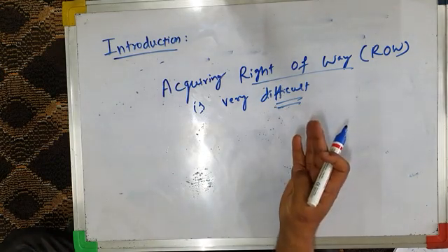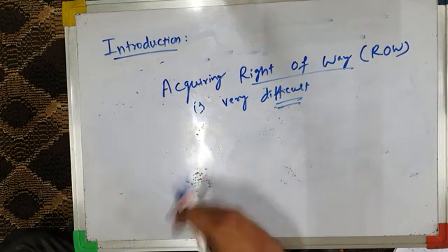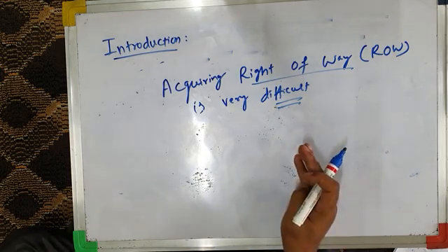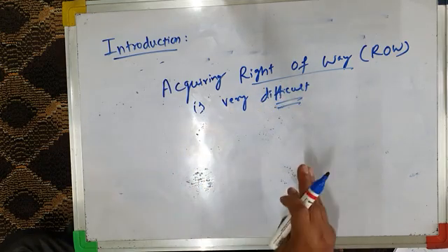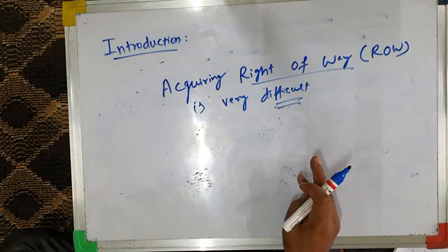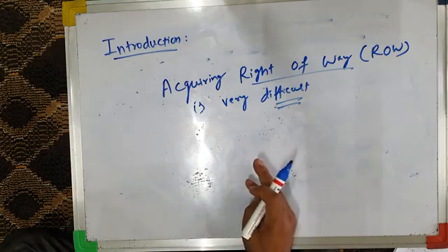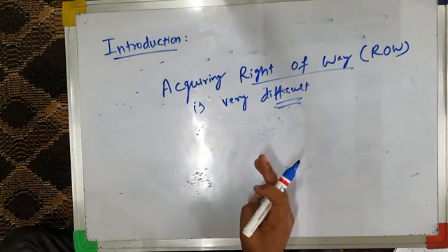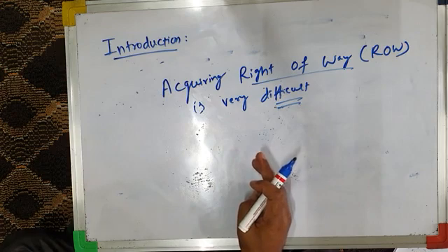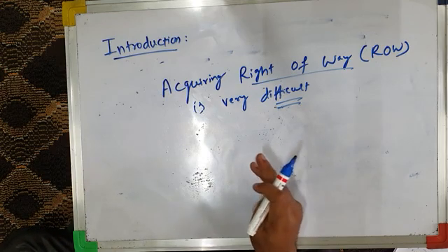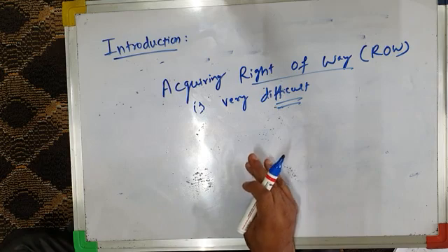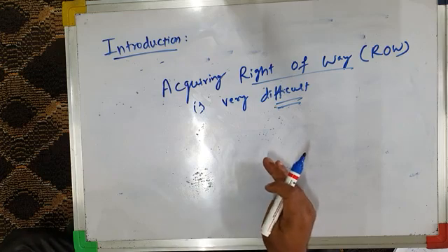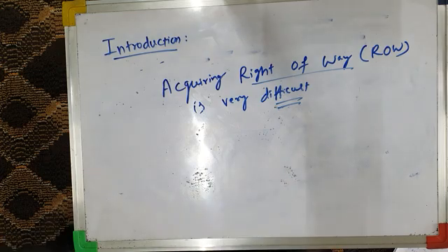One of the problems is that there will be uncontrolled flow of active power over various transmission networks, which will make some lines overloaded and some underutilized. Second is that there will be uncontrolled reactive power flowing over the transmission system, and hence it will decrease the power transfer capability of the transmission lines. Third is that the transmission systems will be subjected to power oscillations even by small disturbances. Fourth is that the transient stability of the system will not be very high, so it will be an unstable system.